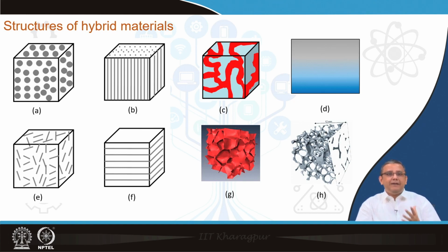Here, image A, the schematic, shows you a particle reinforced composite. The matrix, the white phase, is a typical ductile material, like a metal, and if you want to increase the strength or stiffness at lower density, one can add ceramic particles into a metallic matrix to obtain a particle reinforced composite. One can also obtain, in a ceramic body, other ceramic particles that will enhance the toughness of the material. In case of polymers, they are typically not called particles, they are called filler materials.